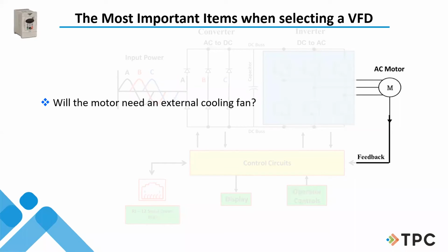And you're going to need another motor starter and contactor. So whenever you turn on the drive, that fan's going to turn on, and that fan is going to blow like that motor's running 1800 RPMs all the time, keeping that motor cool regardless of the speed that it runs. Okay, so that's another one of those considerations you have to think of when you're going to put this drive on this motor. So there's lots of reasons, and they do great things, but we've got to set them up properly.